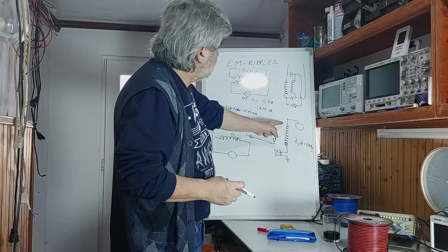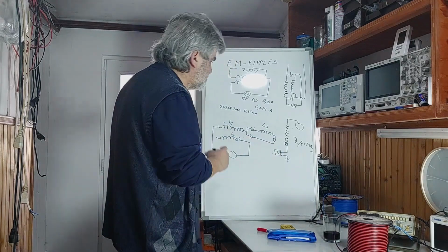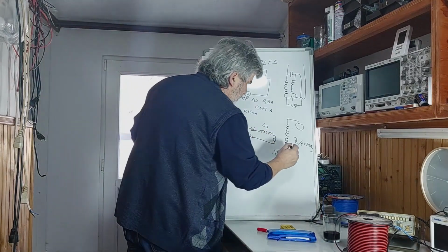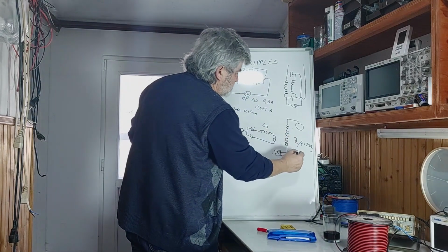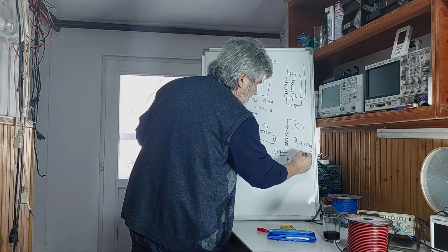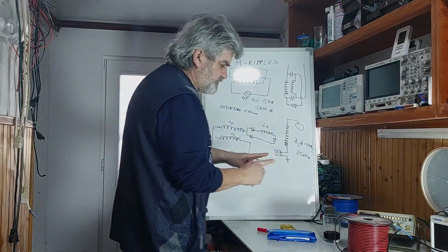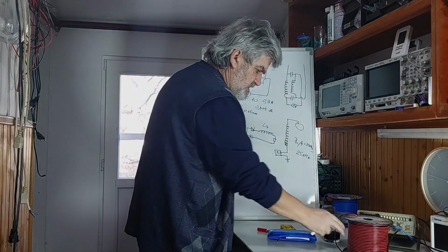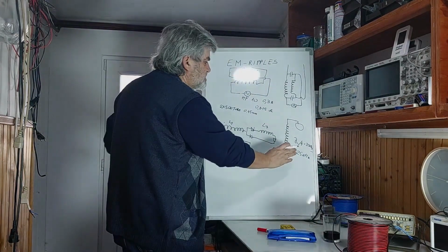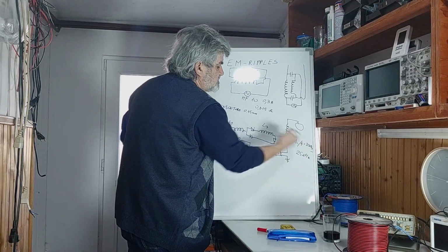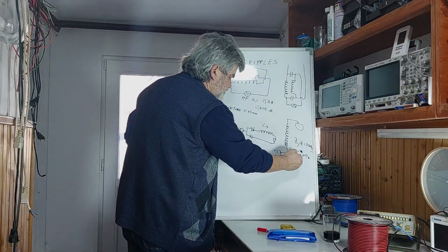And if you put it like this, bipolar, it is almost 10 times less, which means the resonant frequency will be about 25 kilohertz. It depends on the thickness, the distance, the type of dielectric and so on. But it reduces the resonant frequency to 10 times less.